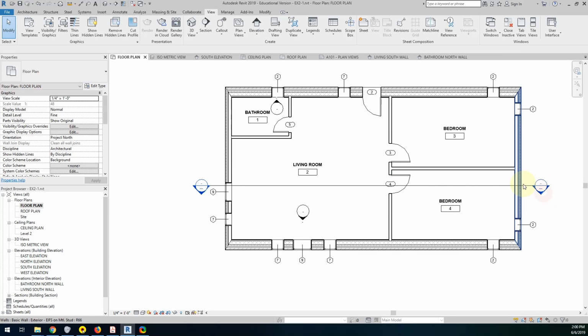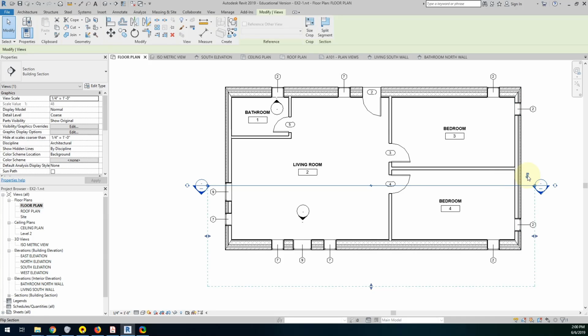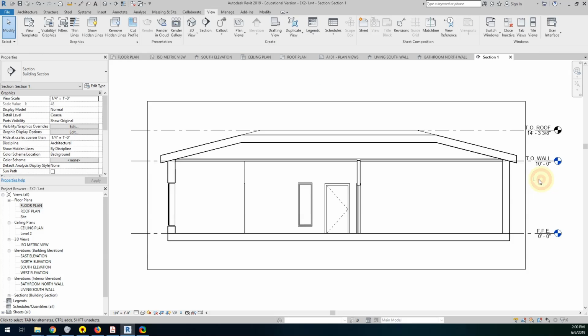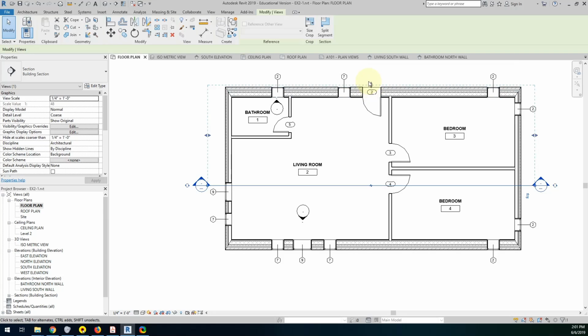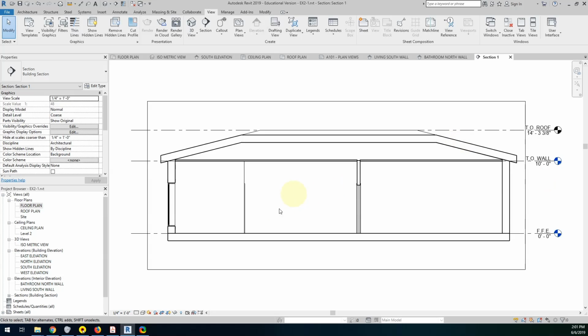If I click to the head or select the line, click that little double arrow, like flipping doors and windows or walls. Now if I double click on that head, I see the opposite side of the room, and the window and the front entry door. So you want to make sure that at least this range here includes the far wall. Again, if I didn't have it include that window and door, I would see no window and door.